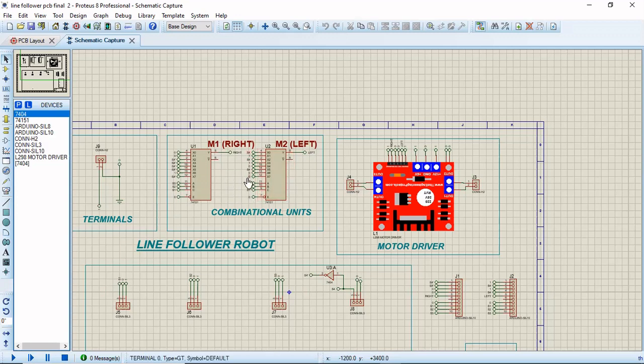Then these are the data inputs, as I have already discussed the connections of these ICs. Then for pin 12 we have ground, pin 13 is also ground, pin 14 is connected to the S4 output, and pin 15 is again ground. And 5 and 6 are the outputs. The fifth pin is connected to the output of the left motor.